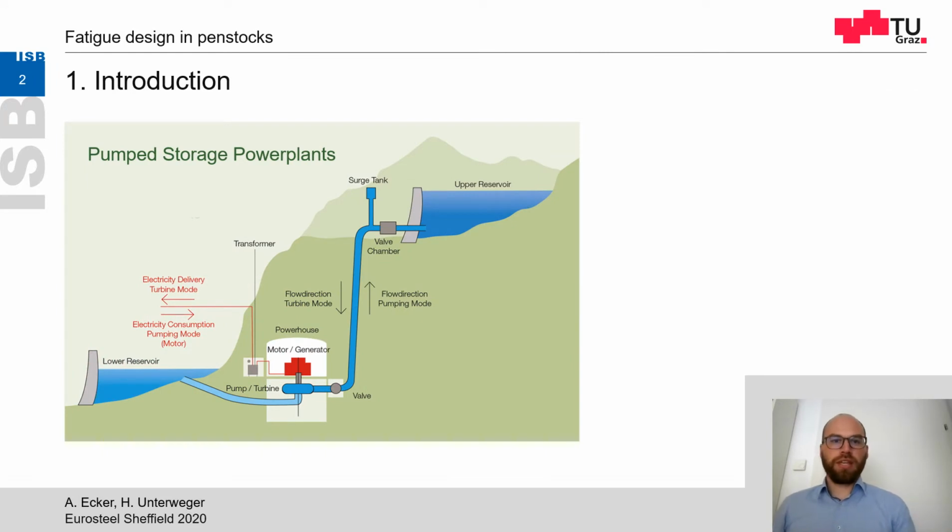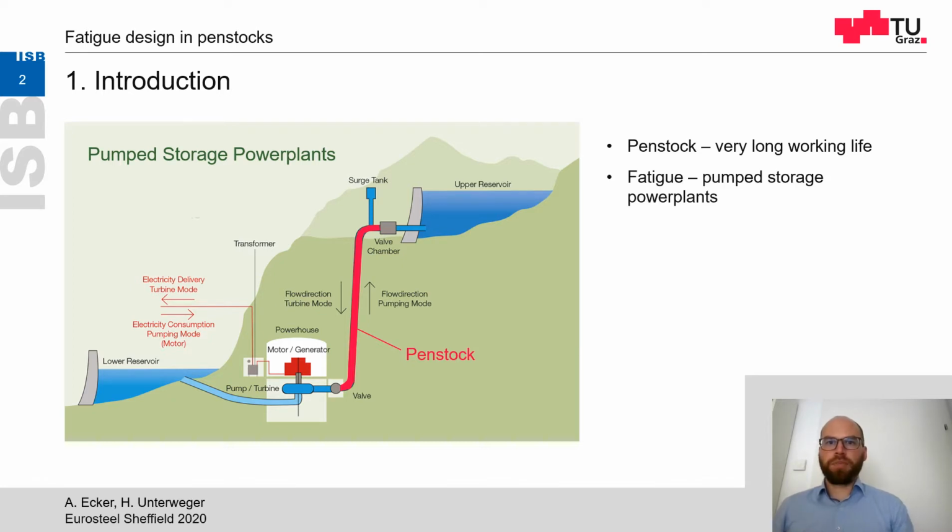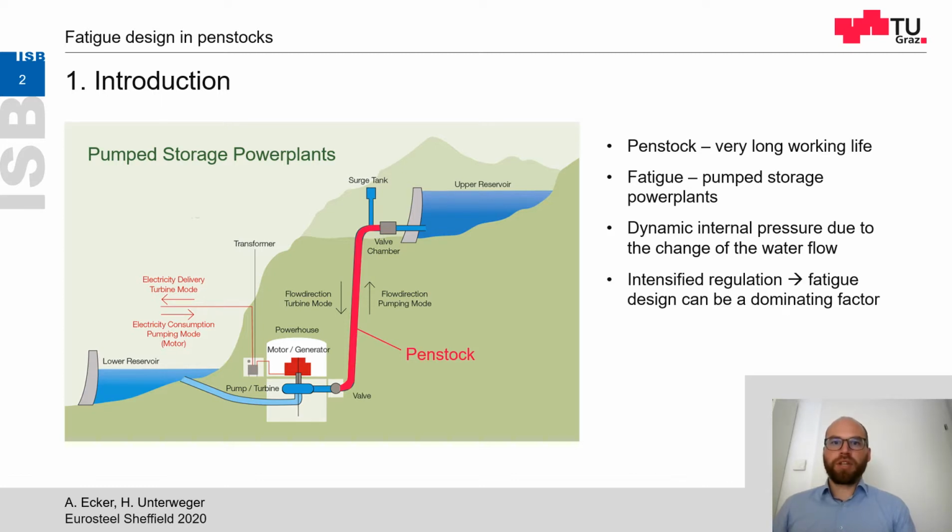Now I'll show you the scheme of a pumped storage power plant. The penstock is highlighted in red. These penstocks have a very long working life, and fatigue phenomena have to be considered, especially in pumped storage power plants, because the change of the water flow causes a dynamic pressure. And nowadays, with the increase of renewable energy and the intensified regulation, fatigue design can be a dominating factor.